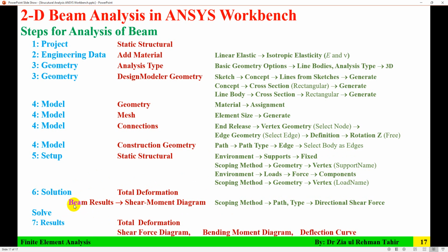There is a built-in parameter: in beam results, you can add the shear moment diagram. Then solve, and you can go to results, the total deformation. There you can check where the maximum deflection is and its value, and then you can simply check the shear force and bending moment diagrams and the deflection curve.